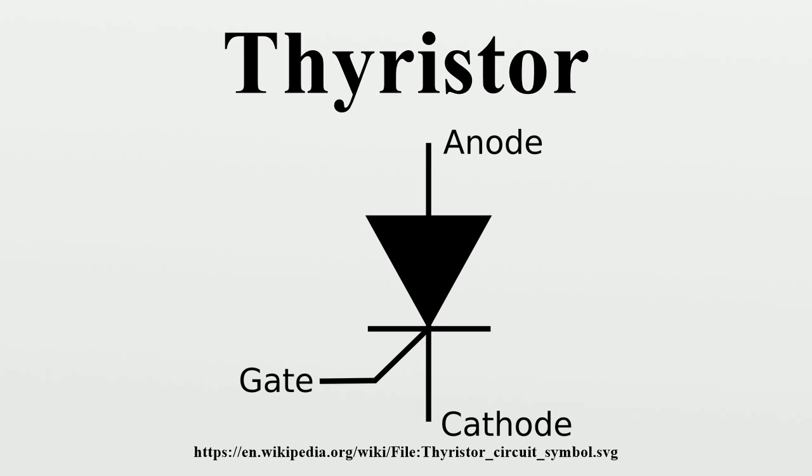Photothyristors. Photothyristors are activated by light. The advantage of photothyristors is their insensitivity to electrical signals, which can cause faulty operation in electrically noisy environments. A light-triggered thyristor has an optically sensitive region in its gate, into which electromagnetic radiation is coupled by an optical fiber. Since no electronic boards need to be provided at the potential of the thyristor in order to trigger it, light-triggered thyristors can be an advantage in high-voltage applications such as HVDC.